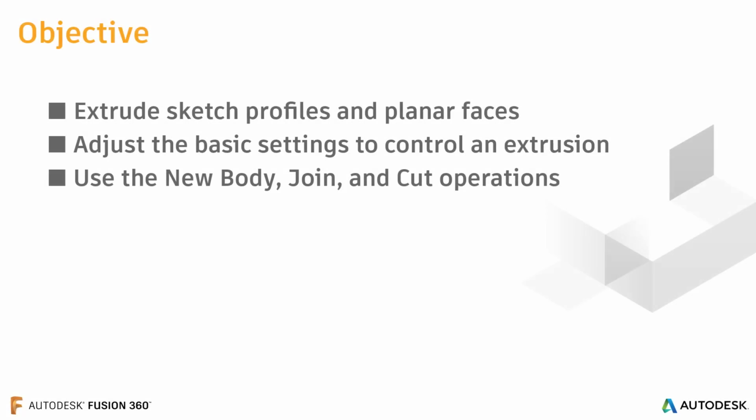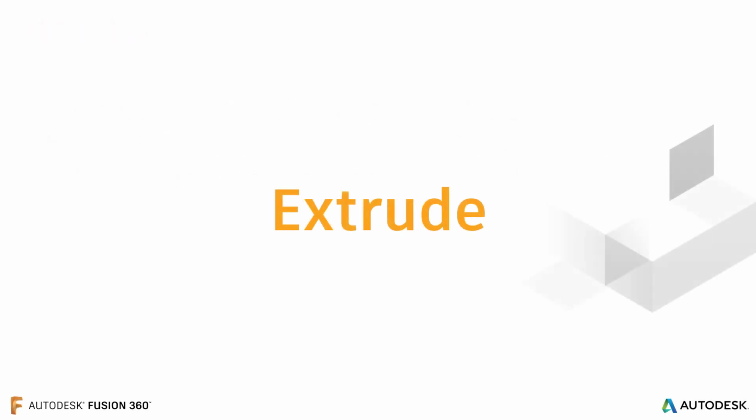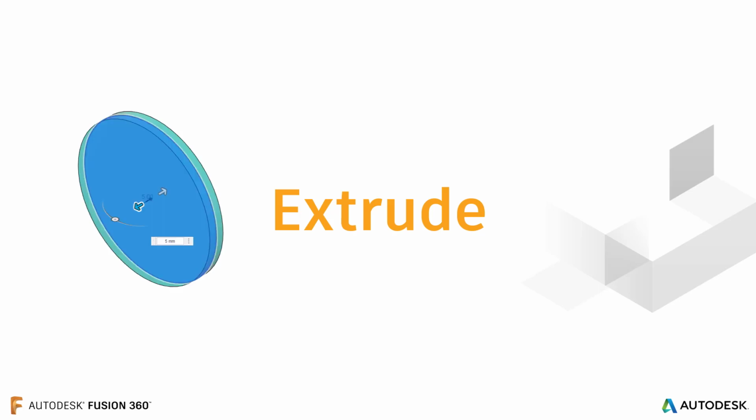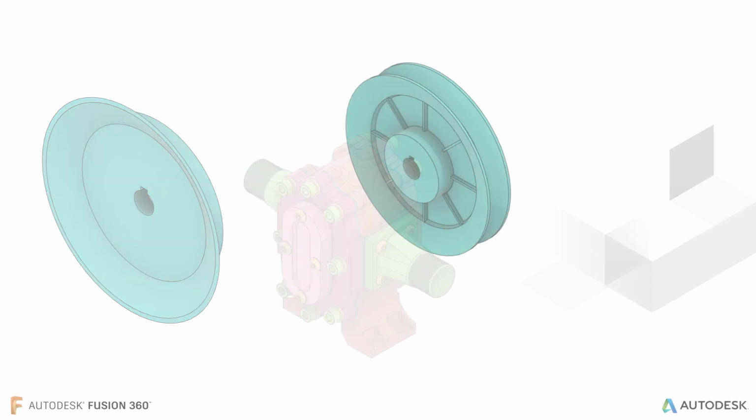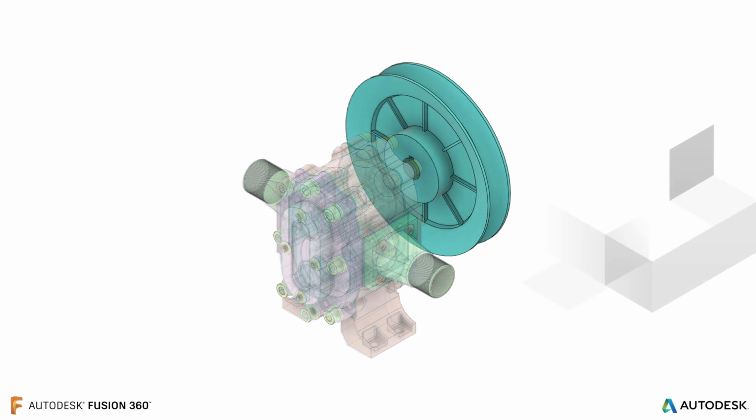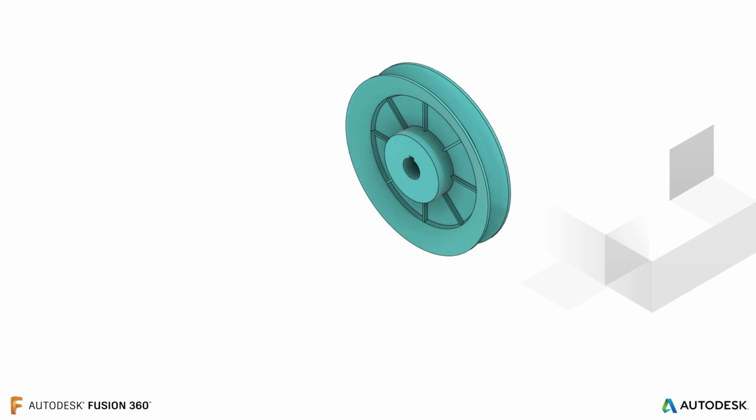In this video, you'll learn how to use the Extrude command to create solid bodies from sketches or planar faces in Fusion 360. In the Design workspace, the Extrude command adds depth to a sketch profile or a face on an existing solid body. Extrude is a versatile tool that can create new solid bodies, or quickly add material to or remove material from existing solid bodies. Let's use the Extrude command to create the starting shapes for a simple component in an assembly.